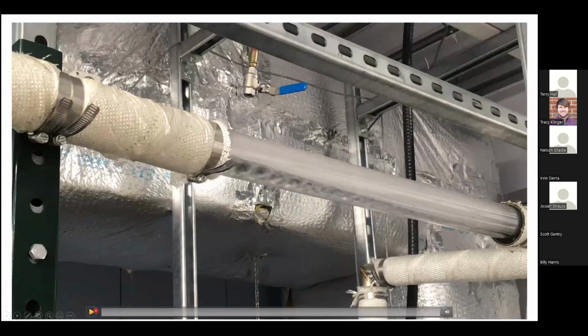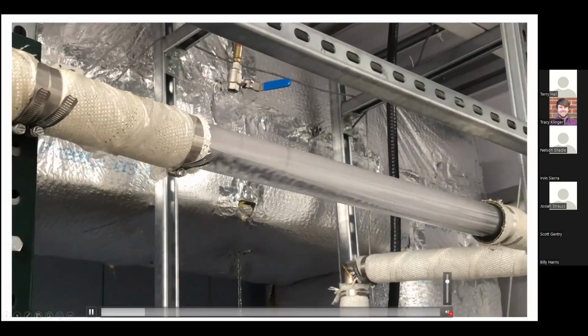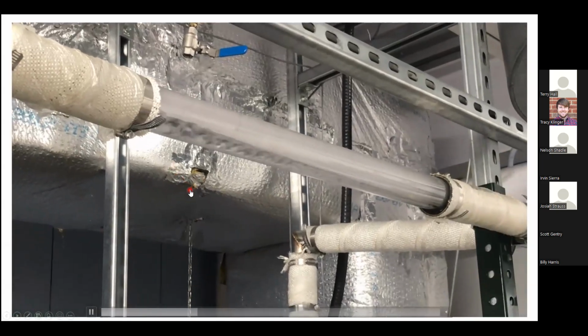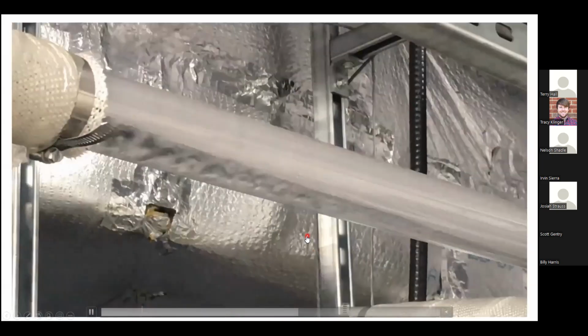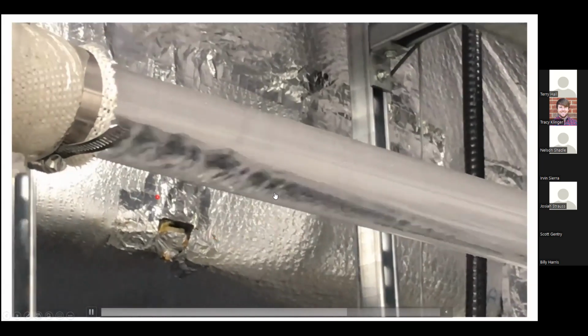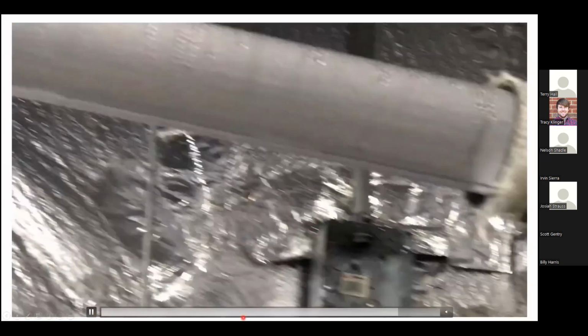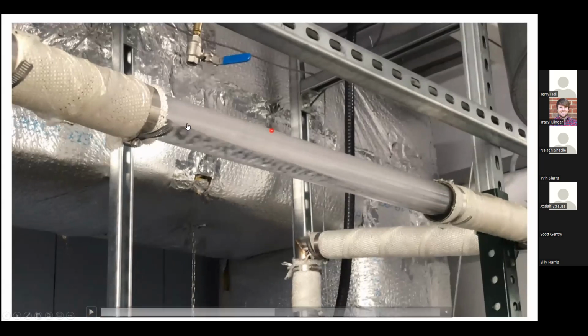Here's just an example that shows you how quick condensate can build up. We had just turned these humidifiers on, and this is a low point in the steam plumbing with a piece of Perspex in there, and you can see there's already condensate that's built up. If this low point were any lower, you'd start really obstructing your steam from the generator to the dispersion grid, and that's going to create back pressure.